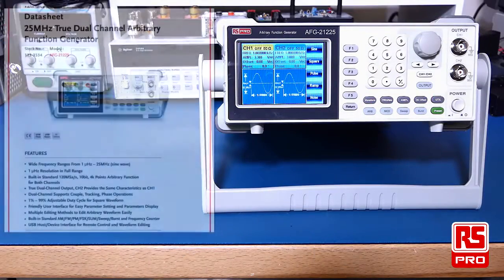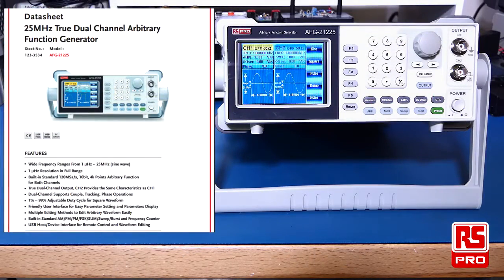The PRO AFG-21225 is a 25 MHz true dual channel function generator. It has a wide frequency range from 1 microhertz all the way up to 25 MHz for sine wave. It has built-in standard 120 megasamples per second 10-bit 4000 point arbitrary function generator for both channels. It has dual channel support coupling, tracking and phase operations.